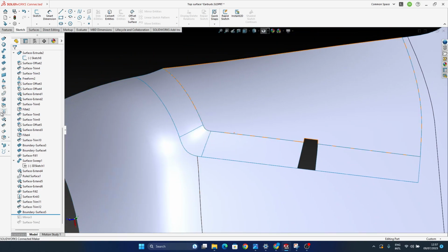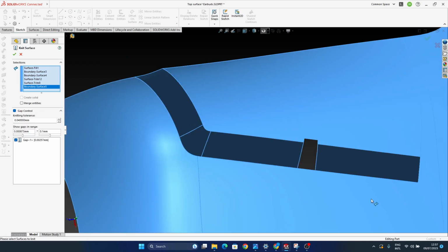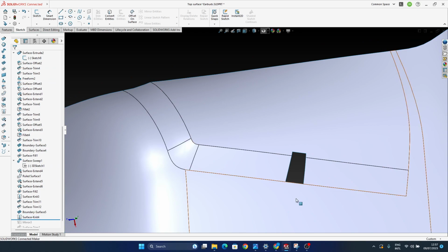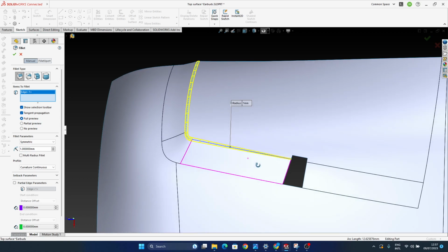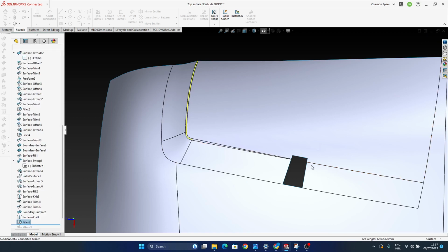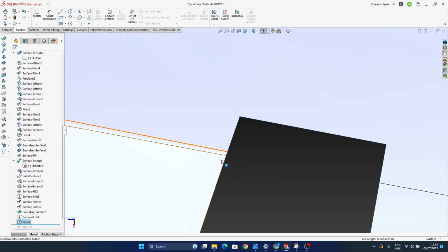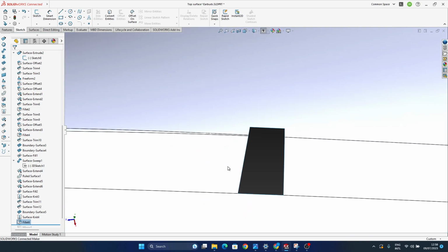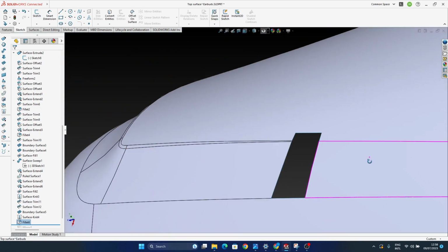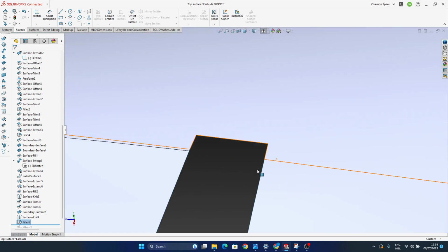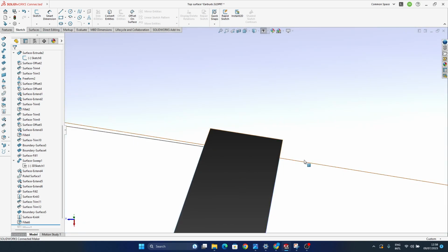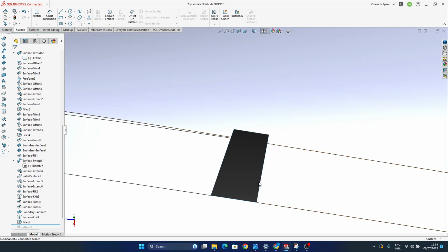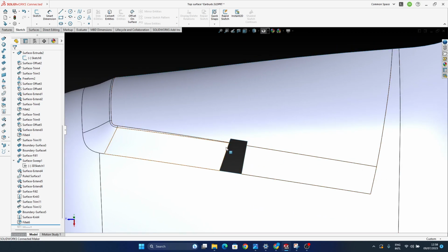So that means going to join all this together. I shouldn't have a problem. I'm going to apply a fillet in here at 0.5 millimeters. Okay, which will give me that and would give me a straight edge in here, which is what it should be. Yeah, but because we applied that cylinder, it is stopping in here, and from here we can always blend all this together nicely.